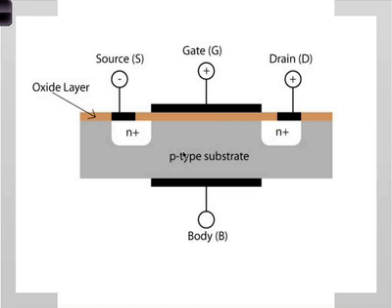You have a P-type substrate, and you have an N plus region. You apply a gate voltage, you apply a positive voltage, you push away the holes, you create depletion, you put enough positive voltage, you attract electrons, create an electron channel, an N channel. Okay? So positive voltage creates an N channel, negative voltage for the other type creates a P channel. Signs are reversed.